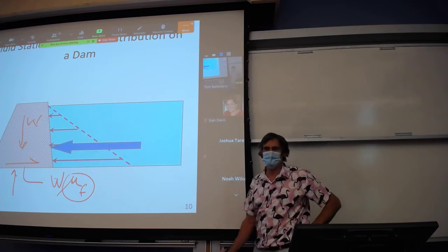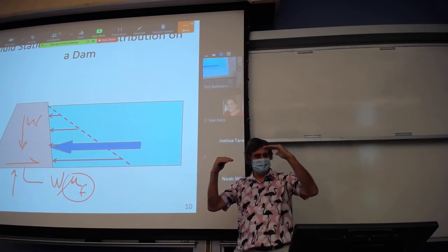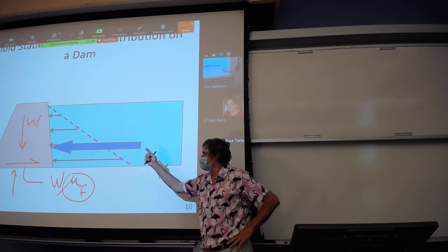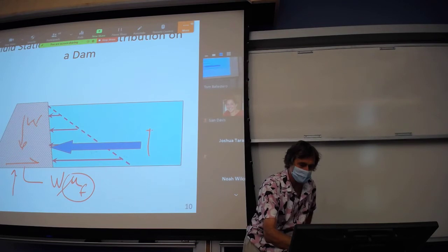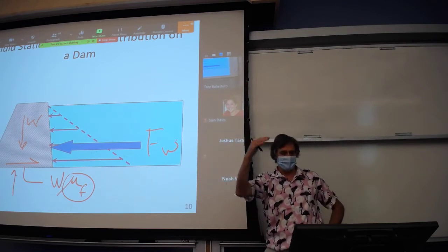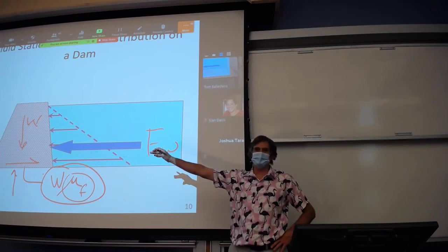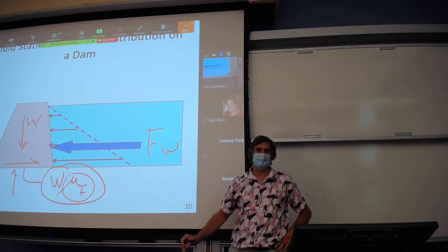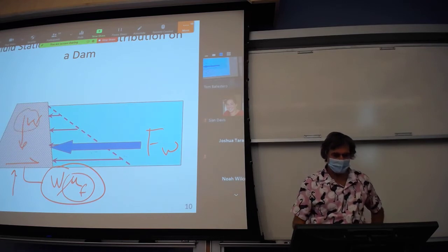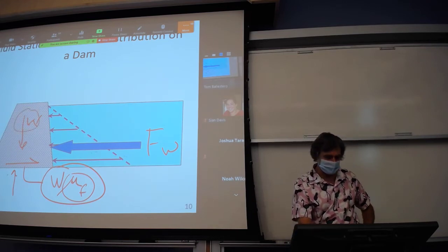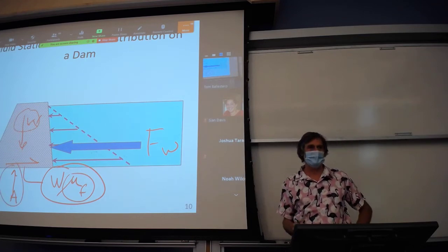I think that's what they use, μF, for solids. And so the resistance that the dam had, if you looked at the sum of the forces in the horizontal, is that the water force horizontally on the dam would have to be equal or less than the resistance of the force to movement in that direction. That would help you, in this case, design the weight of the dam as well as the surface area over which that weight acts.